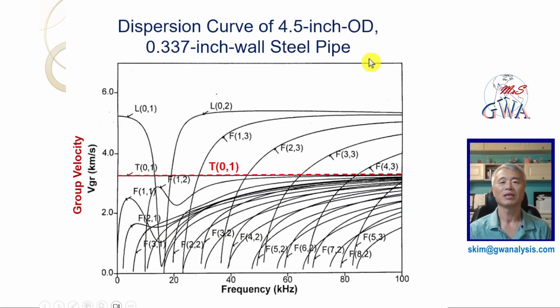We are back to dispersion curve of pipeline. The only non-dispersive wave mode is T01, and all other wave modes are dispersive. For increasing spatial resolutions, the transmitted signal uses one-cycle tone-burst RF signal that is broadband with a wide frequency spectrum. All dispersive modes are curved lines so that the group velocity changes as the frequency changes. These dispersive modes cannot be used for long-range ultrasonic testing due to broadening of wave packet.